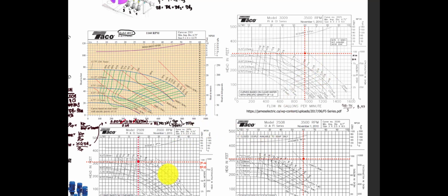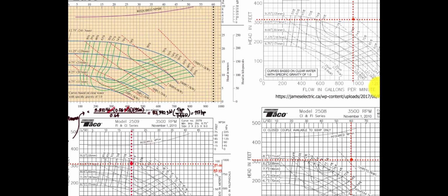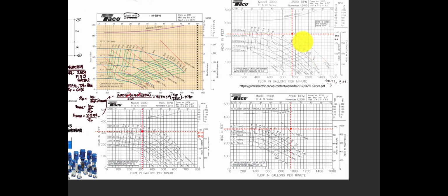There may be an error in this pump characteristic curve. But if you continue the curve of this impeller at 20 liters per second at this given total dynamic head, you will still reach near 100 horsepower.